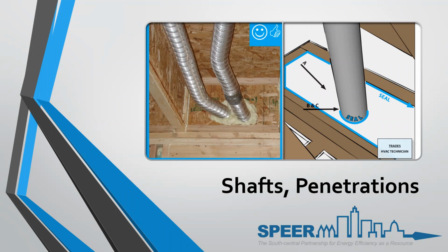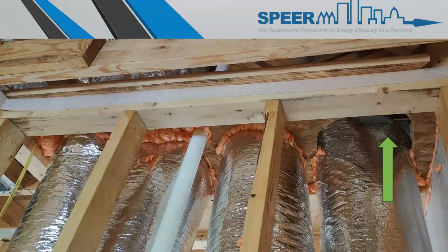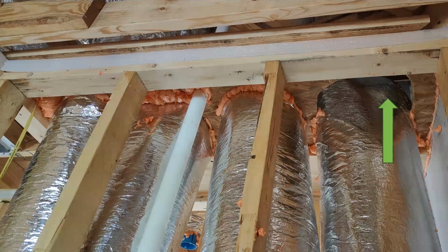Basically, what you're doing is you're identifying the envelope. On the right-hand side, you see a duct or a flue going through there. They have identified that that is part of the thermal boundary. And so they're going to put that alignment there, and they're going to block it and seal. And on the left, you see two bath fan ducts going through the band joist, which are also being air sealed at that point. So these all must be blocked and sealed in order to separate the conditioned from unconditioned spaces. A great example here of a duct chase. So in order for the ducts to run to the attic, a chase has been created.